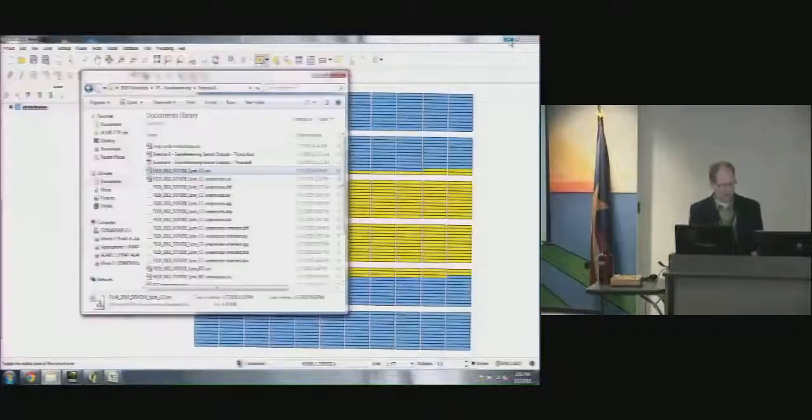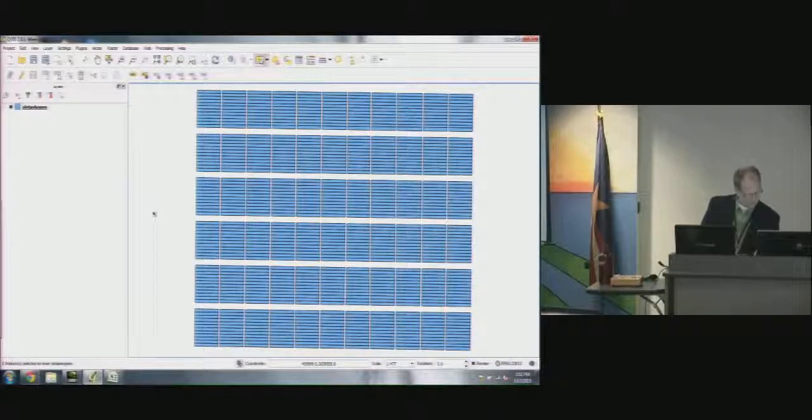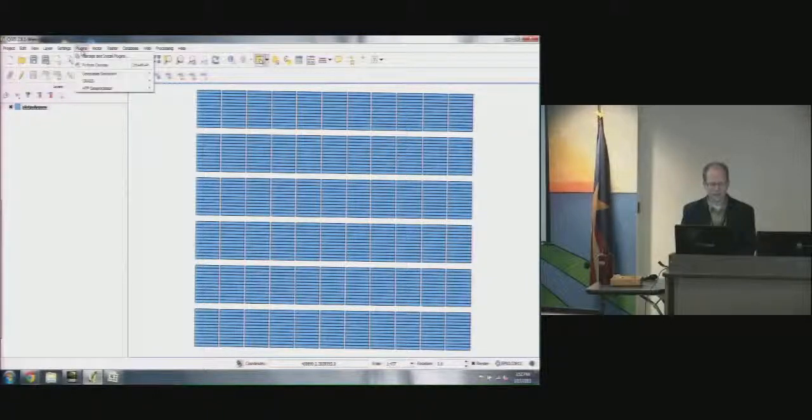Okay, so we can load that information in Quantum GIS by selecting... the first step is to pre-process that information. We can't load it in Quantum yet and view it on the map. We have to first pre-process it and do the step of calculating the UTM coordinates and transforming the positions from the GPS receiver to the actual sensor. And so the tool that helps you do that is called the preprocessor.